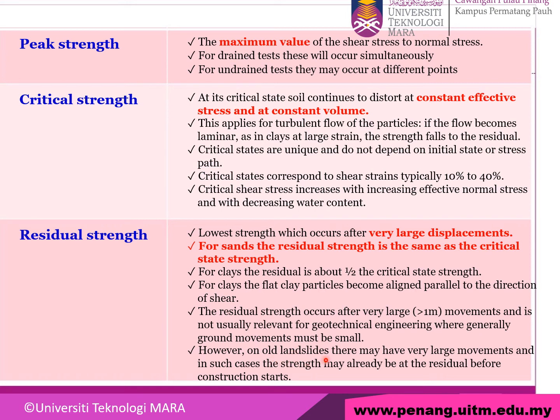However, in old landslides, there may have been very large movement, and in such cases the strength may already be at the residual before construction starts. That's why sometimes failure happens.